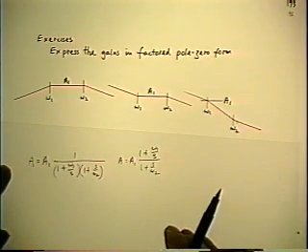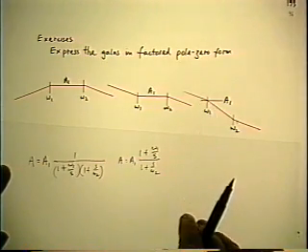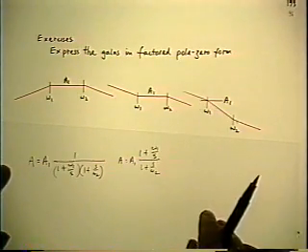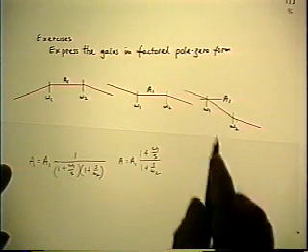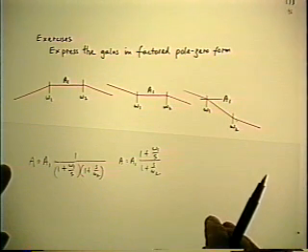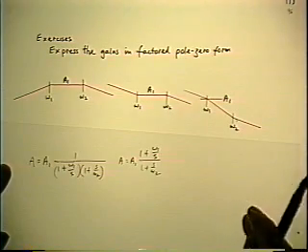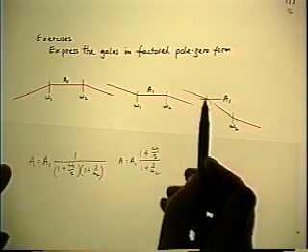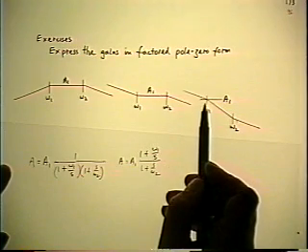Third one, no flat gain. But there's an identified reference gain at a certain frequency, omega 1. The tricky thing is it's on two asymptotes. But that's an advantage because you can identify it on either one of them at your choice to choose for the original reference. Probably the simplest choice is to identify it on the left-hand asymptote, since that's the first one.